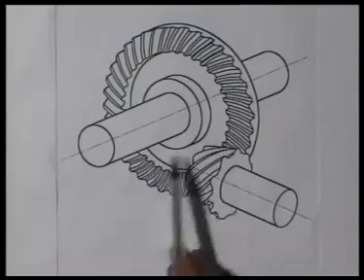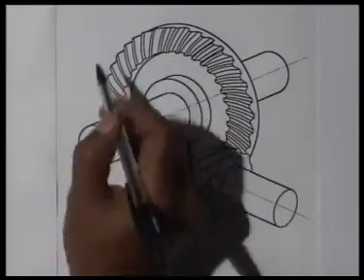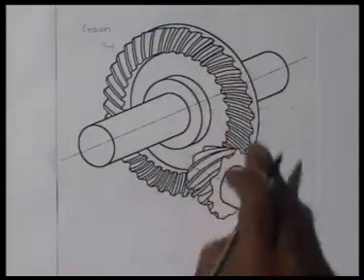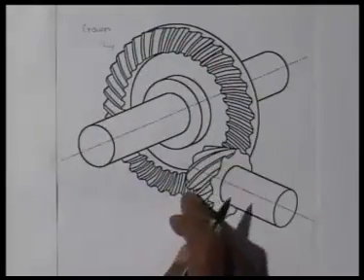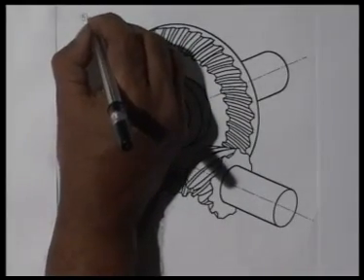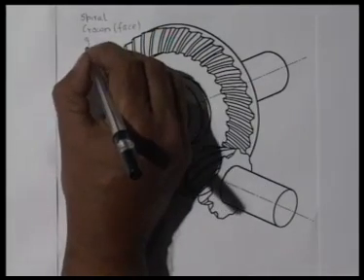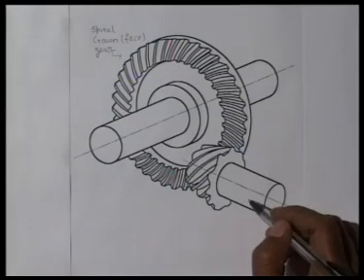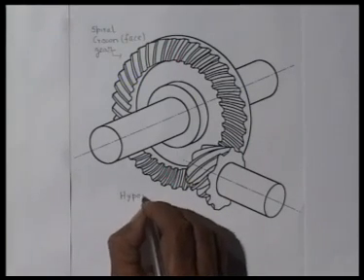This diagram shows what I call a hypoid gear. The thing to note is that they look like bevel gears and the gear teeth are in the form of a helix rather than straight. So this is a crown or face gear, because the semi-vertex angle, if I think of this as a cone, is 90 degrees and the gear teeth are lying on the circular track. So this is a crown gear but with spiral teeth, so we can call it a spiral crown or face gear. And this gear is in contact with this gear. As I said, these are used in automobiles with this as the input gear and this as the output gear, and this is called a hypoid gear.